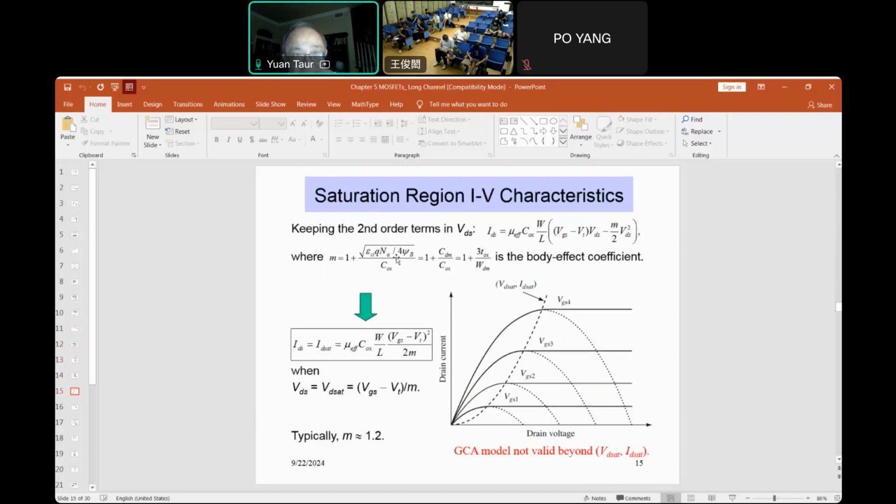This is CDM. CDM is the maximum diffusion capacitance. In other words, if you put psi s equal to 2 psi b in the MOS diffusion capacitance, you get that. Okay. So CDM is epsilon silicon divided by WDM.